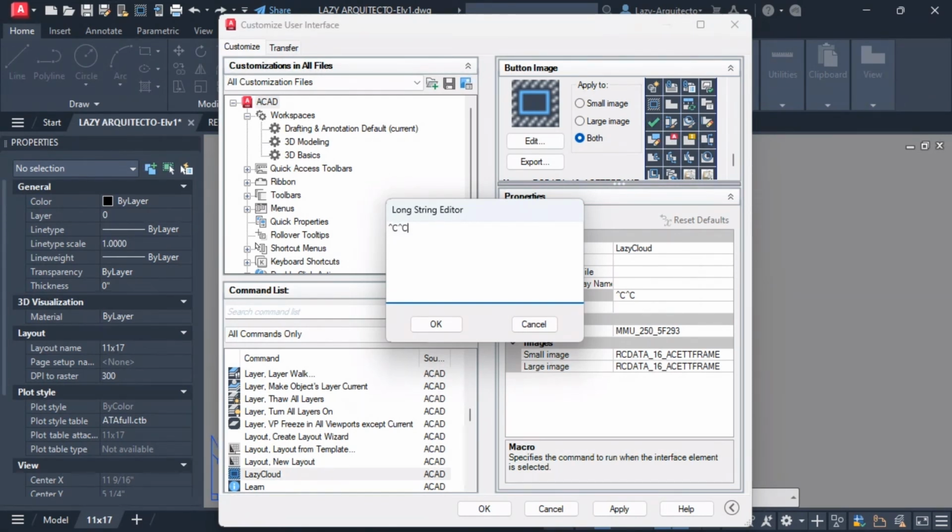Next, I'm going to use this small piece of code, that is the rectangle command. That's the way a revision cloud also is drawn, by clicking 2 points on our screen. We're gonna need to start the revision cloud command, revcloud, and with the option to select the arc.